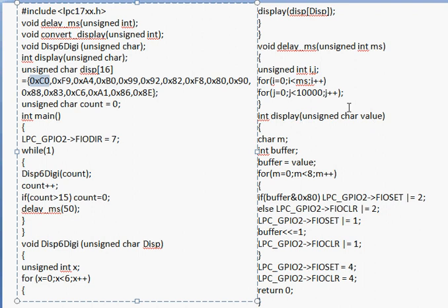So it has value C0 now. Okay, it has value C0, and it is character m you have defined. This m is required for iteration, because in your data, C0 data, you have 8 bits. The buffer is also defined. You can define it as character, so it will be better. And what you do is, first you store this C0 value in buffer.